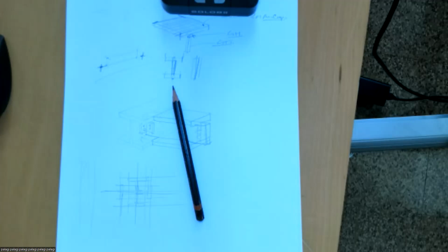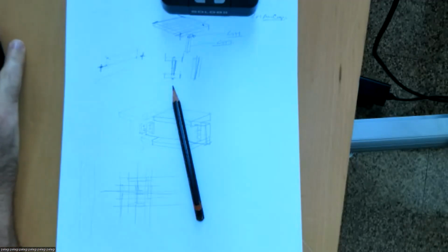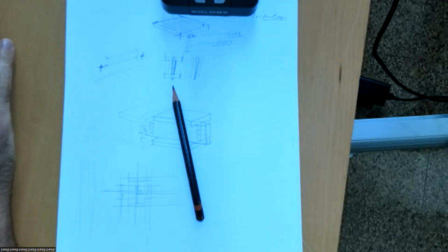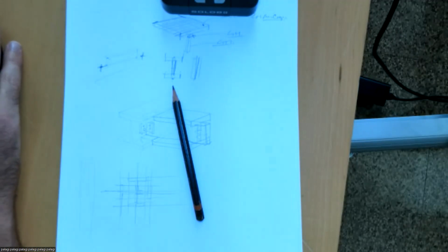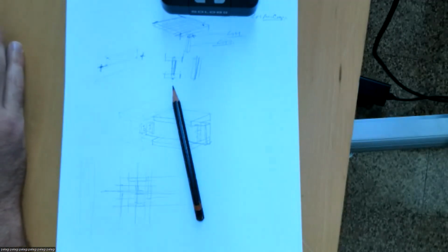We control, exactly, when we grab something in another file and I touch something, you have the ability to make a family parameter there. Or if there's a dimension and I grab it and hit that, that's making a family type, create a parameter. If I go into here, I can just make them and assign them. So all of those, there's just the idea that you're telling it that I want to control it later.